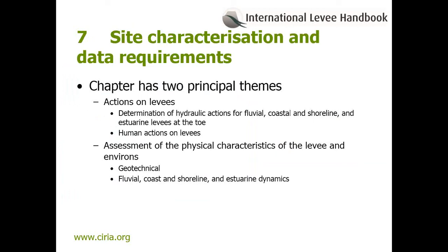The chapter can more broadly be divided into 2 principal themes. Actions on levees, that's hydraulic actions. These can be considered to be what nature throws at the levee, and human actions. These are things that we do that load or cause change to the levee. The assessment of the physical characteristics of the levee and environs.